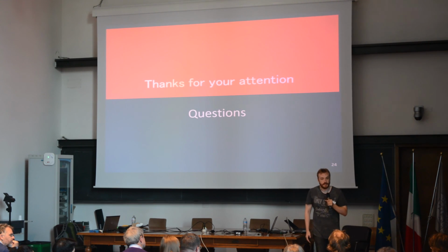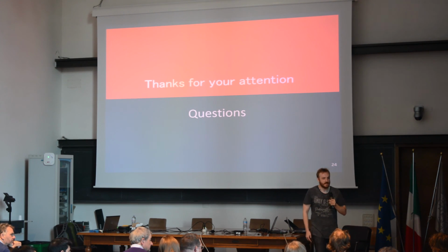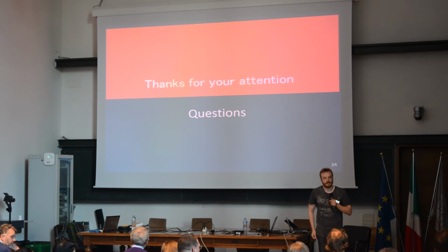Yeah, so I can explain what happens with your branch predictor when you operate on large memory sizes. Yeah, we know that. CoreMark doesn't have so many branches inside, and G-share, thanks to its implementation, just caches all branches, and when you iterate multiple times on CoreMark, you get almost exact branch prediction.